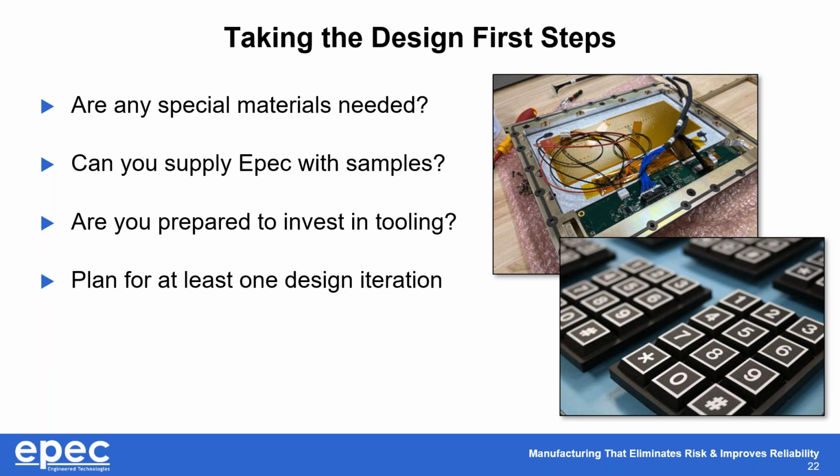With that said, any new part like this is going to have some NRE to go recreate it. Whether it's a simple die cut overlay, where NREs could be a few $100s, to a custom membrane switch with a touchscreen panel, where NREs could be a couple $1,000s, to a full front panel that's qualified to mil standard A10, where NREs could be tens to even hundreds of thousands of dollars. You must be prepared to invest in tooling to recreate a lot of these parts.